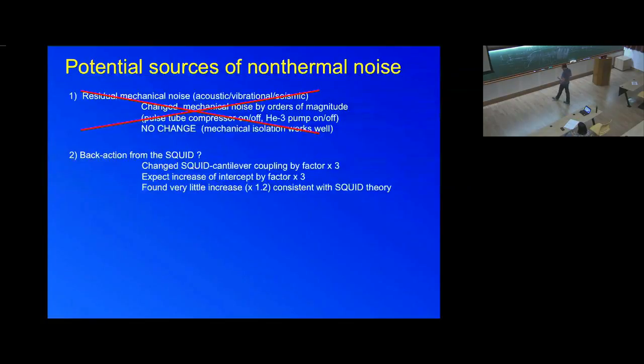But what happens is that when the frequency becomes very high, there is no complete penetration. You have the so-called skin effect. Basically, the magnetic field can penetrate only a layer, which is called the penetration depth. And inside, you don't have magnetic field. The surface currents which are induced by the field are completely shielding the field. So that's more complicated. You have to do it numerically or using some very complicated form.